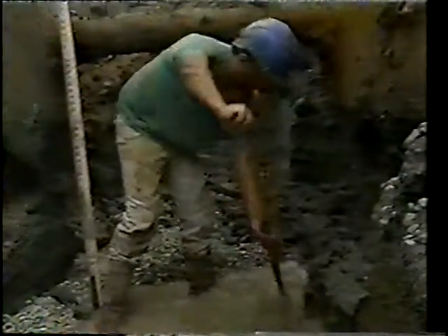The particle size of the bedding is important. Large particles can cause a point load on the pipe and can damage coatings. In high groundwater areas, clean, free-draining gravel can serve as a drain. If the gravel exceeds the allowable particle size, it must be placed below the bedding itself. This means over-excavating the trench bottom and placing a stable foundation layer.